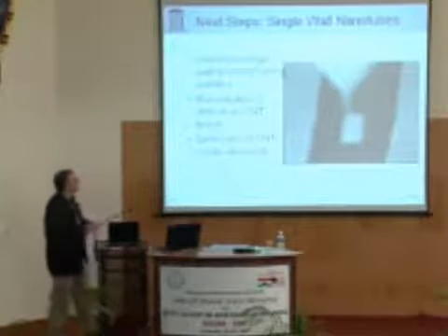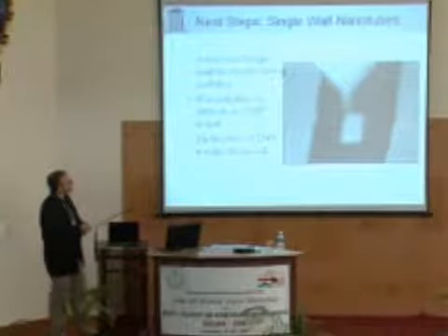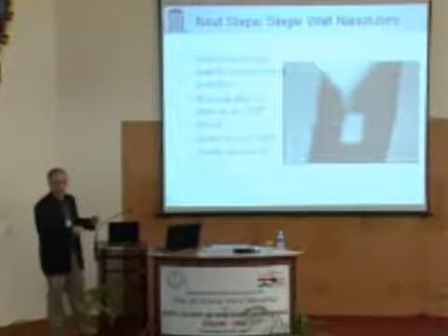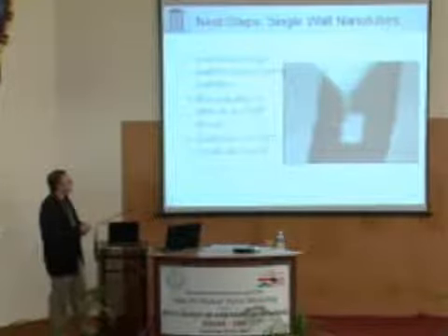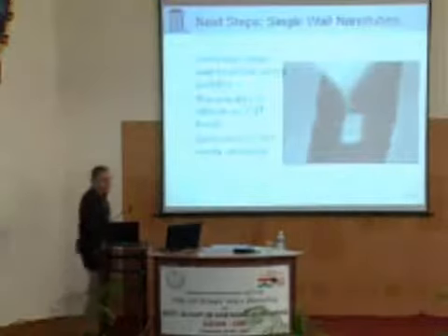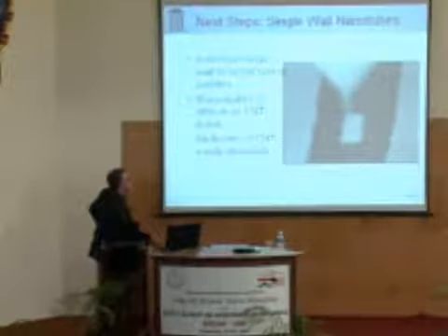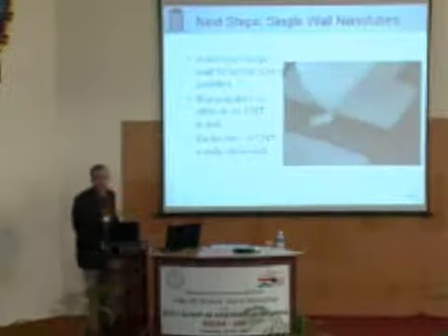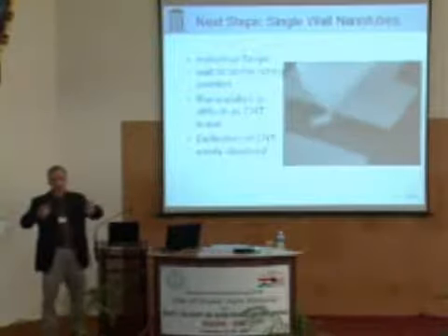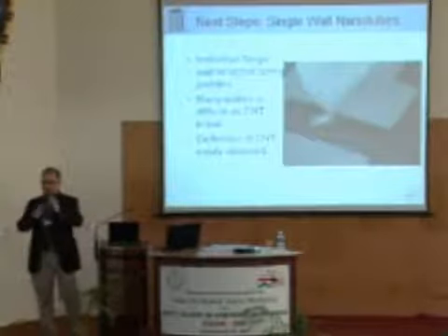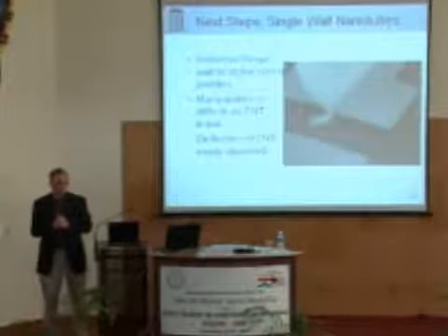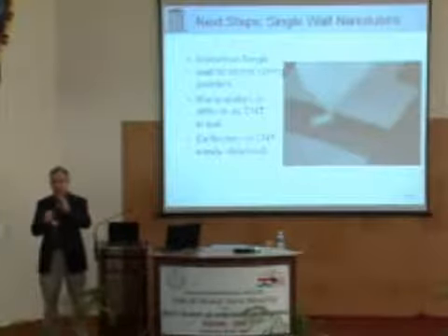So moving on, we have since also created, over the last 2 years, individual single-wall nanotube torsional oscillators, or torsional devices, where this nanotube here is 1 nanometer in diameter. The measurement becomes very difficult, though, because the torsional stiffness of a rod from continuum mechanics goes as the 4th power of the radius of the rod.